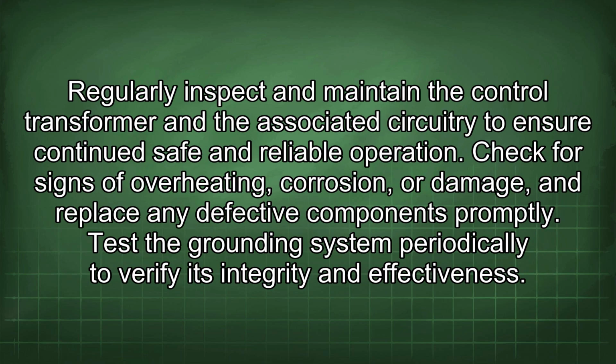Regularly inspect and maintain the control transformer and the associated circuitry to ensure continued safe and reliable operation. Check for signs of overheating, corrosion, or damage, and replace any defective components promptly. Test the grounding system periodically to verify its integrity and effectiveness.